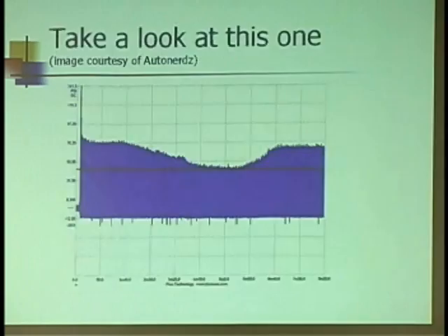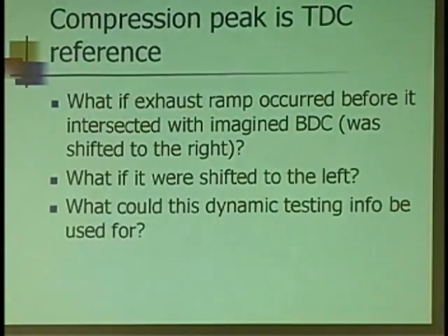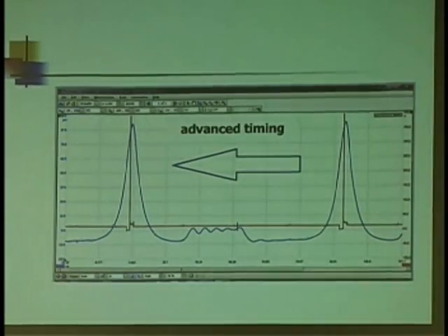Okay. So what you're going to be looking at is this portion right here, this moving here. And if you wanted to test the VVT, you could use the bidirectional control to command it off and on to see if it was working as it should and moving as far as it should. I could take my paint cursors and measure the amount of degrees it moved, okay, to compare.